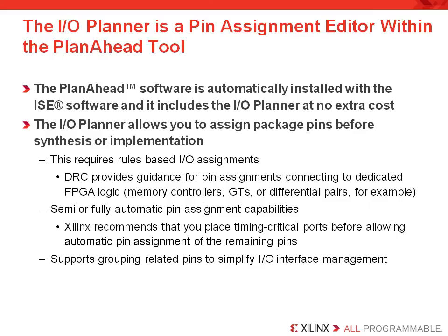Now keep in mind that any pin assignments you make do not assure high speed. They're built to help you get good performance by placing pins near the dedicated hardware. It is still possible to make pin assignments where the implementation tools have little choice and are forced to place some routed logic further from the pins than we like. This can be caused by poor HDL that creates timing critical paths, or a tight internal timing constraint that forces the internal paths to be considered a high priority. We will talk about pin layout recommendations in a few minutes, so hopefully those tips will help you meet your timing.